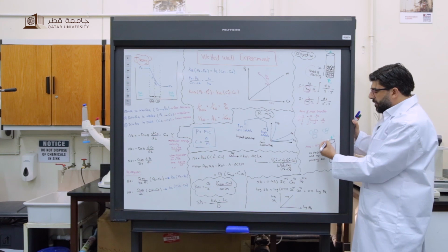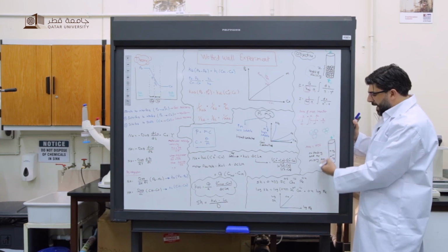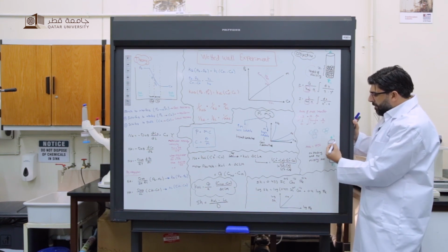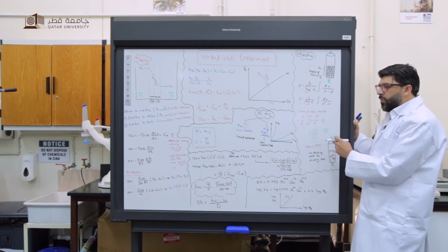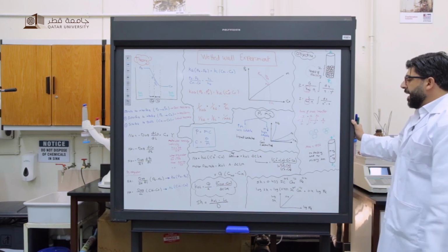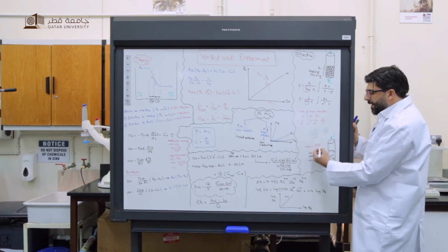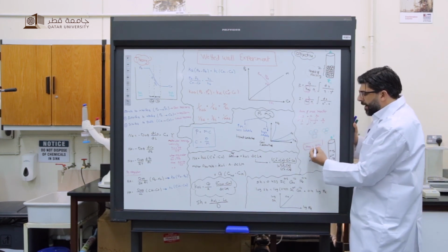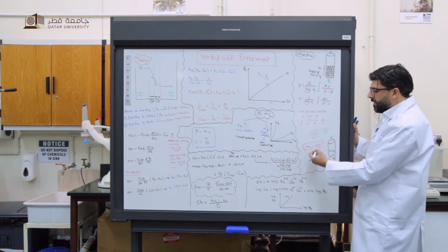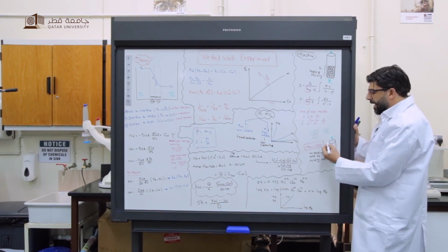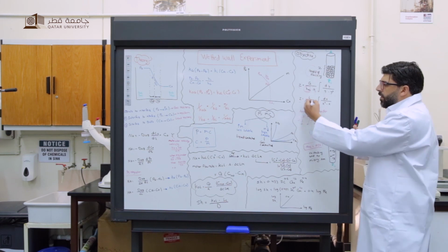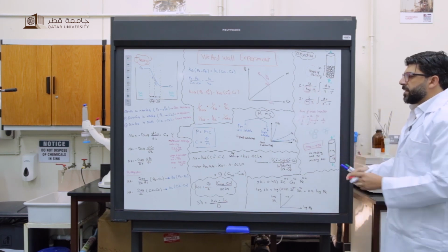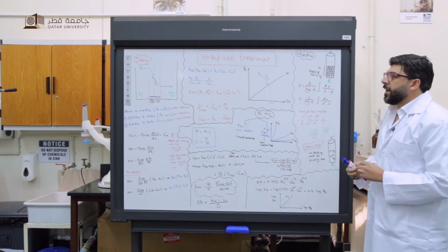The liquid phase flows countercurrently with the gas phase and makes a film along the inner wall of the column. Then the area is simplified to pi d L. It's very simple. Since I know the diameter and the length L, I can find KOL or KOG without any mistakes. This is the objective of today's experiment.